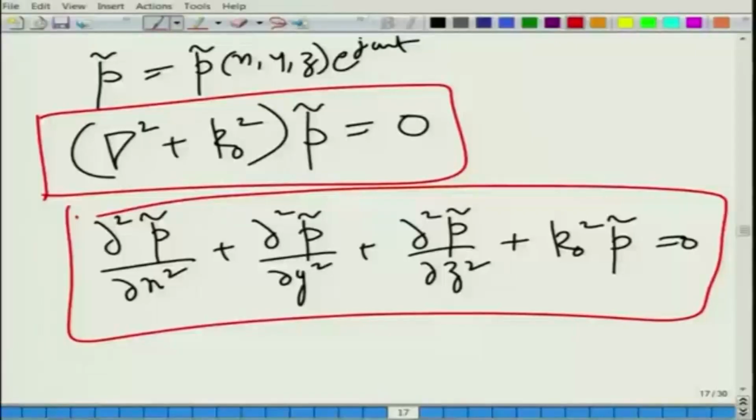It's relatively straightforward, and then that equation is your Helmholtz equation in the Cartesian system with flow along a certain direction. That is to say, the equation that governs wave propagation in a rectangular waveguide, but with mean flow along the axis of the duct. Then we can go ahead and impose the boundary conditions and all that.